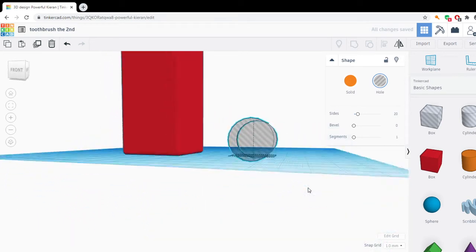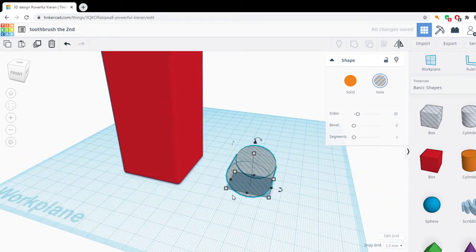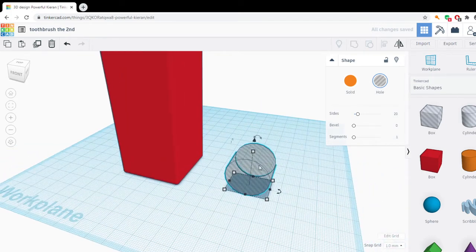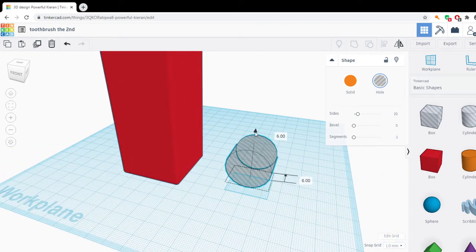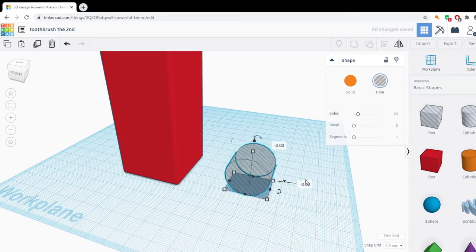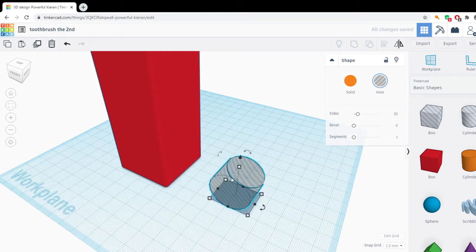Now what I notice about this is this actually syncs through what's called my work plane. That's what it's called on all these CAD programs, these computer-aided design programs. I'm just going to go up to 0 here, and that means that I'm just sitting nicely on the work plane. If I go above that, and it will usually go up in increments of 1 millimeter, it will automatically tell me I want to go back down to 0, and that will bring me down to 0. I'm going to use a keyboard shortcut, and I'm going to use Control-C, Control-V to copy this.